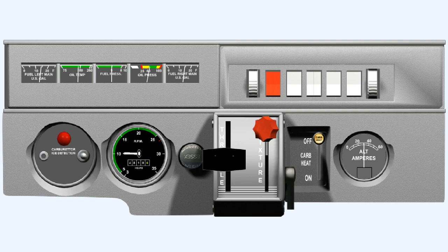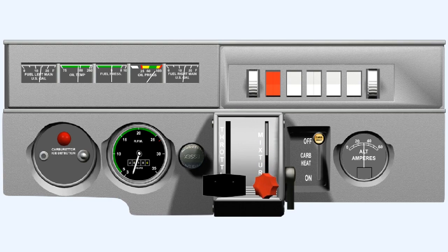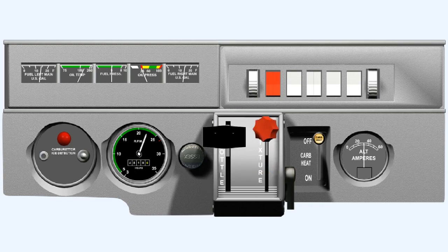As was stated before, as long as the oil pressure drops to normal as the engine warms up, this situation can be considered acceptable. However, if the pressure rises to dangerously high values, the engine must be stopped to prevent damage. The oil pressure should be within its operating range at the correct operating temperature. High oil temperature could cause the pressure indication to be low. If the oil pressure is too low, apparently because of associated high oil temperature, then this is probably due to the viscosity of the oil dropping below the point where the oil pressure relief valve can cope with the situation.